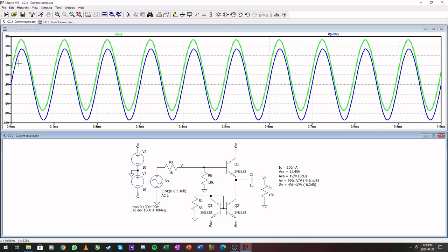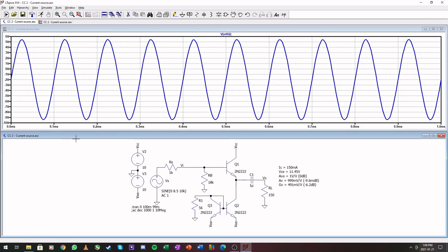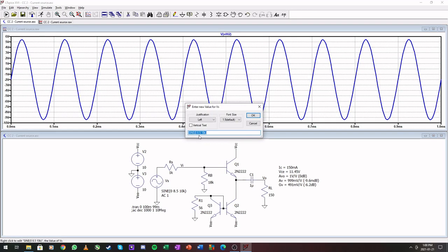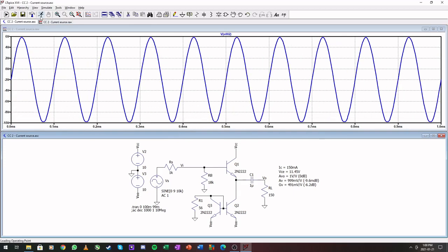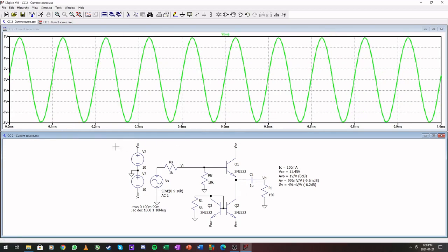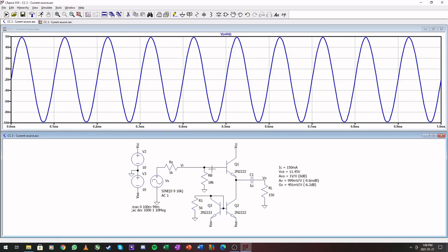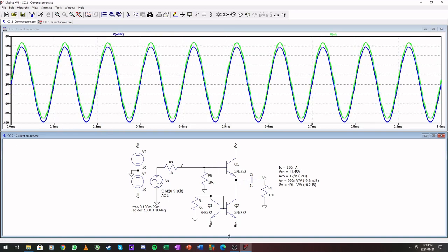So you can see how the effects play out, and here we have an almost -2 drop, and that is where our saturation will take place. When this moves down too far, it will start to flatten the bottom here. So if we make this 9, we might see that starting to happen. There we go. Starts to flatten at the bottom, and that obviously translates right through our amplifier. Okay, and that is it for common collector.